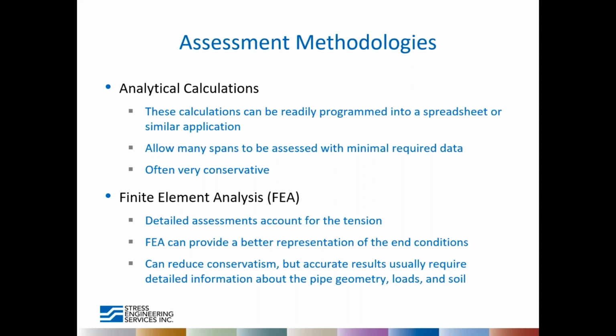With a finite element analysis, on the other hand, we can get detailed assessments that account for things like tension and other stresses. The FEA can give you a good representation of the soil boundary conditions as long as you have accurate knowledge of what your soil properties are. And you can also model different end conditions like supports and things like that.